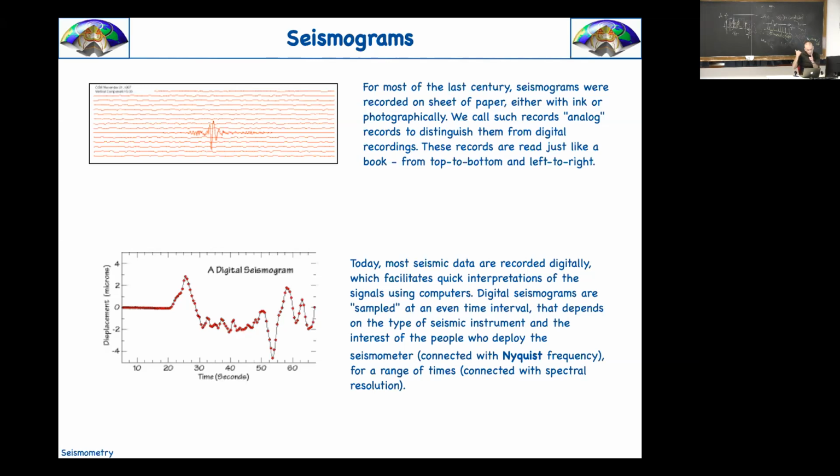So the only way to avoid aliasing and to see frequencies that are not real, because they are fakes, is to have a delta t sufficiently short that the aliases are not overlapping with the original spectrum. That's why the sampling step should be small enough. How small?